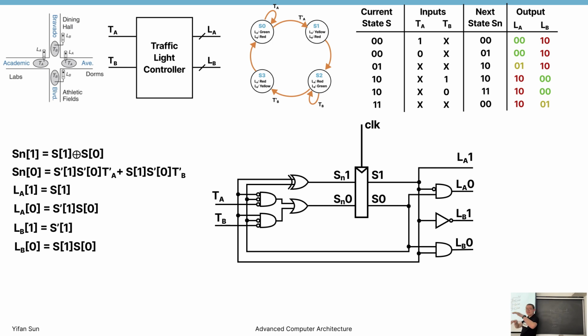Remember, no matter what we change, the next state will only become the current state when the clock signal is a rising edge, right? So it will pass this barrier, go past this mountain only after we see a rising signal. Okay, then the signal will start to generate and we'll loop back. This is a feedback loop.